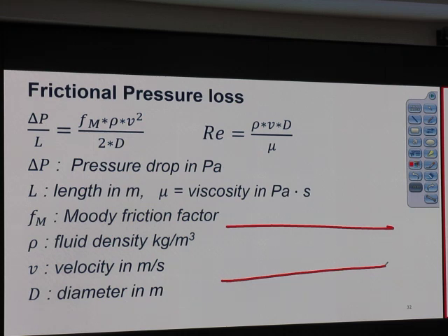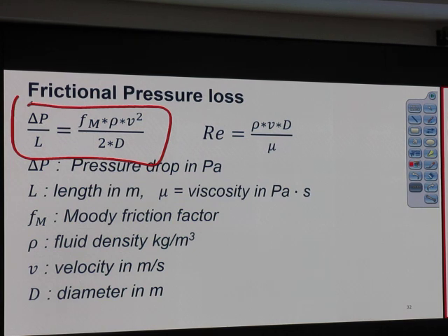But okay, let's say I have a subsea pipeline which is 50 miles, 100 miles. Speed of sound will have some delay, okay? It's not like I turn it on at this end and it will move at the other end right away. No, it takes at most, as fast as it can is the speed of sound. That is the best that it can do. All right, we discussed this already. It's for steady state, fully developed, for both laminar and turbulent.